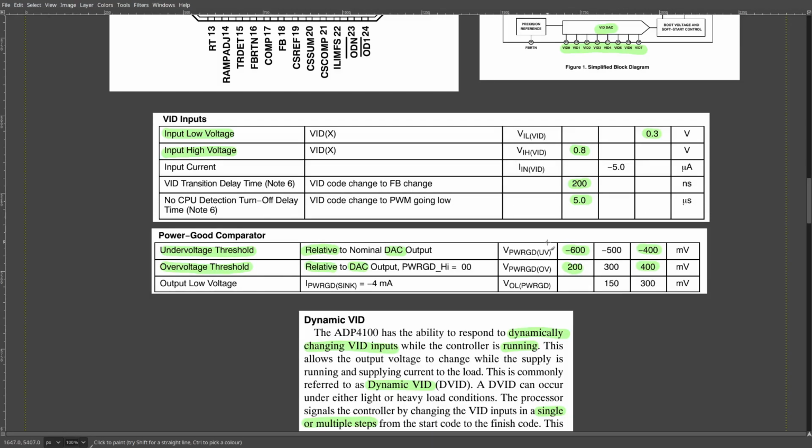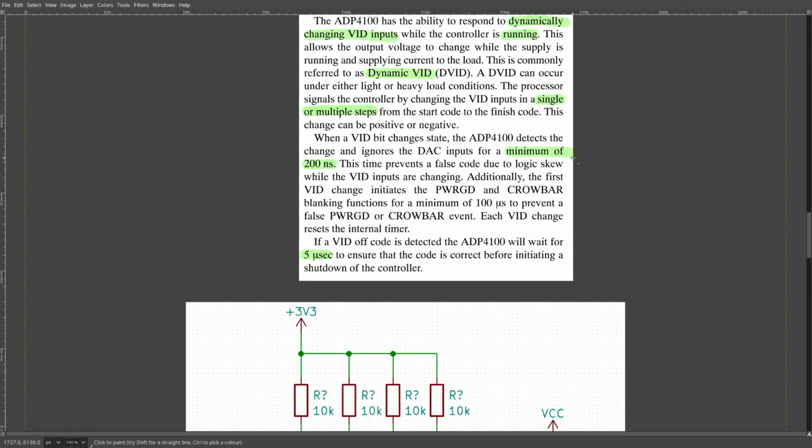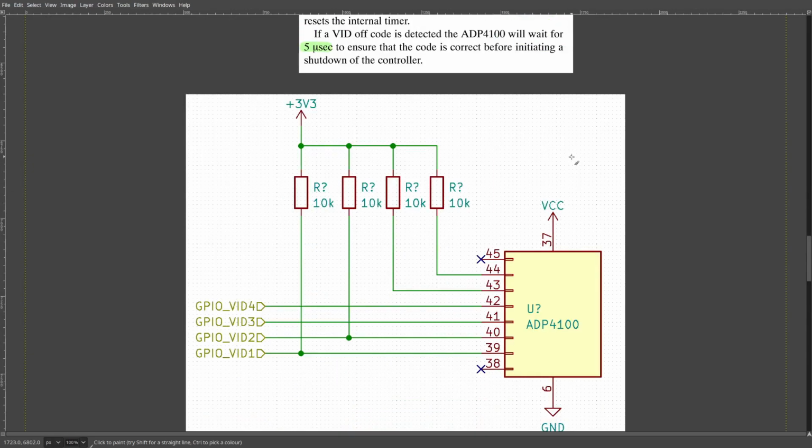Just to check, do you really need this? As you can tell, in both of those cases this is an implementation detail for a microprocessor changing the VID. You are not going to move it that quickly with your hands flipping switches. It's just unrealistic. This is how it avoids the in-between states if the CPU is changing it, for instance.